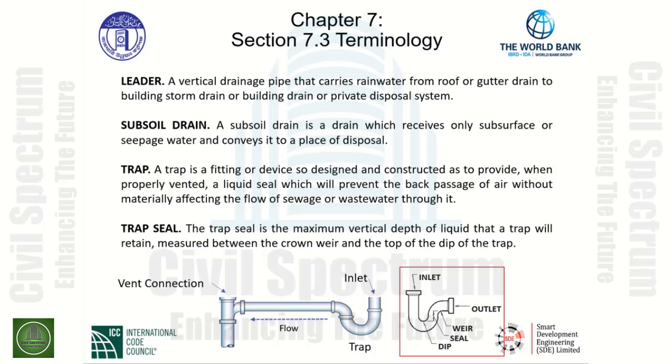The top of the sanitary T is where the vent connection will take place and be piped to an approved venting section of the drainage system. To the right, we have a description of what a trap is, along with the terminology for that particular trap.